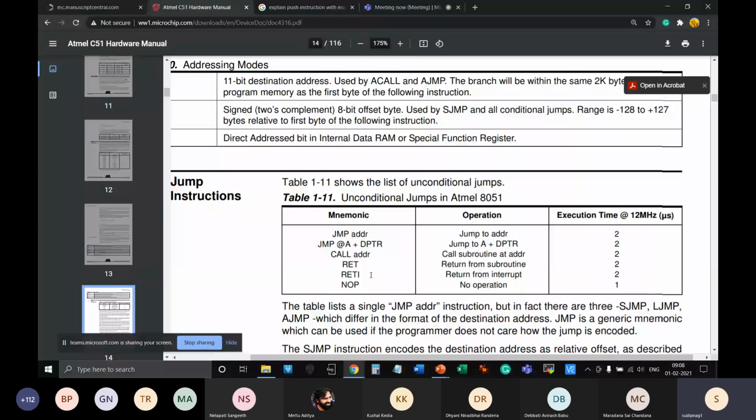Now, after you service the interrupt service routine, which is a type of subroutine, you apply this RETI, and automatically it will invoke the pop instructions two times. But there is one extra thing that RETI will do: it will update certain flags.